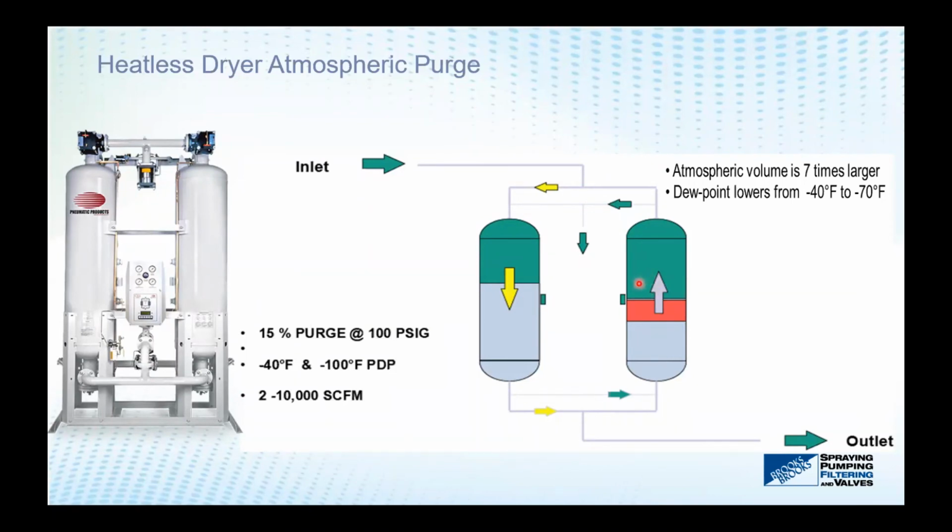And very good concept, very reliable equipment, except the negative aspect of it is you're losing 15% of your compressed air at 100 psi. But it's still one of the most reliable designs, and depending on the flow rates, I'd say below 1,000 SCFM, this is typically the design standard that customers use.